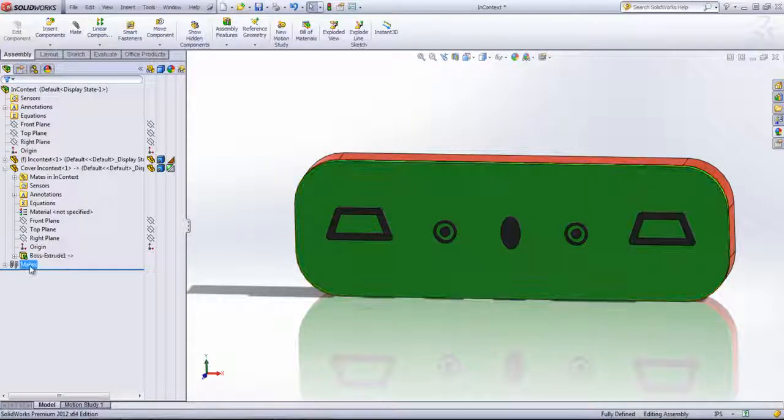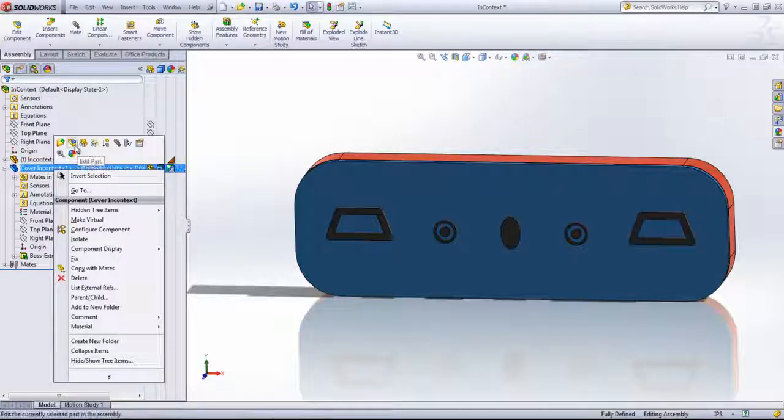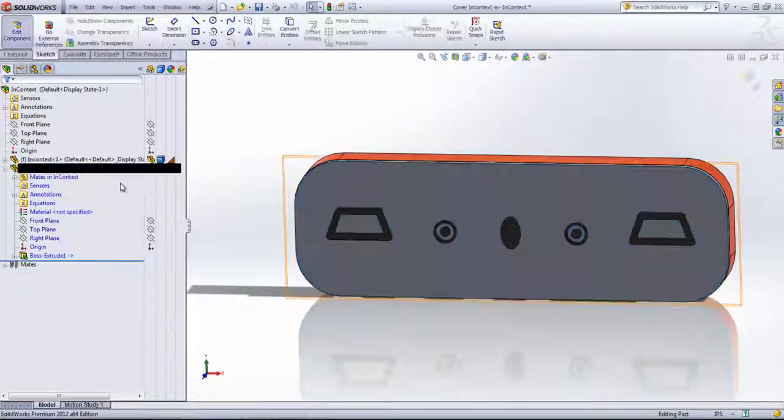The reason for that is you'll have multiple assembly level features, most likely, and it's easy to confuse those items, accidentally delete out a sketch, or accidentally move something around that blows up that entire feature on your part. So just keep that in mind when working with in-context references.